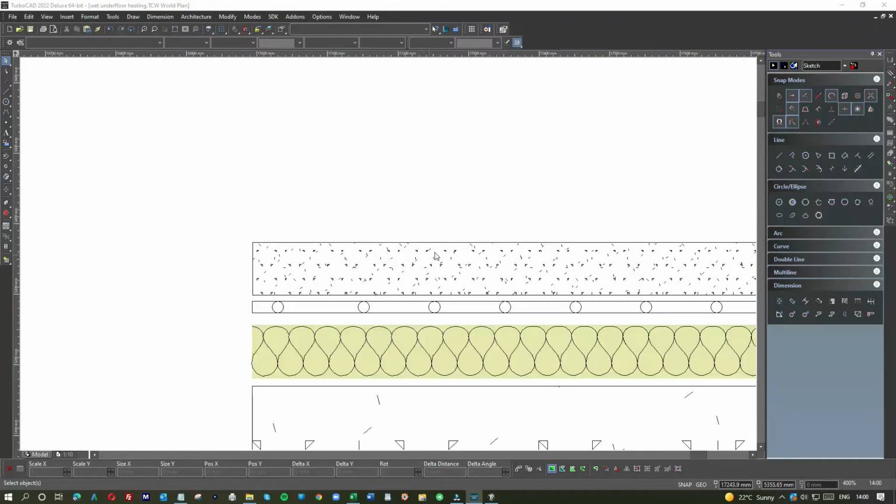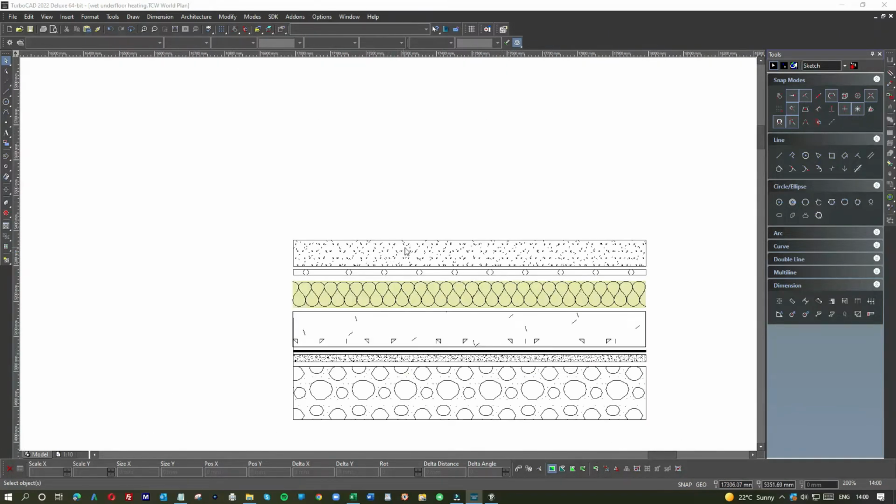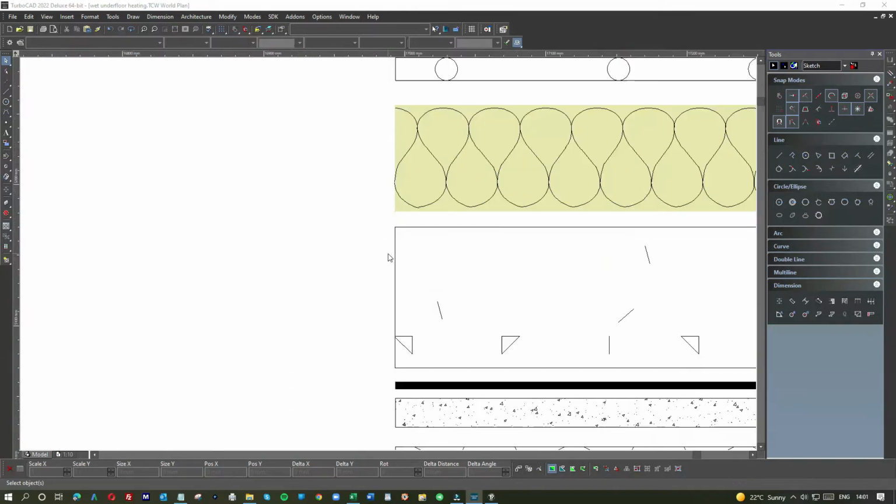So now that's your concrete slab. It's basically called a liquid screed. They come in, they pump that in, and on a large area it can be accurate up to 1 mil, because it finds its own height, it's liquid. And again, if they put a hardener in there, it can be ready to walk on the following day. Cost you a little more though.